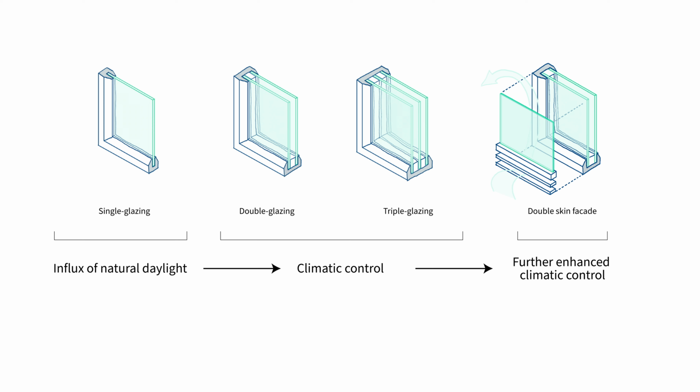The advent of double-skin facades delivered further improvements in thermal and acoustic performance. Double-skin facades incorporate an additional layer of monolithic glazing outside the insulated glazing unit. Natural ventilation is promoted through the external cavity to minimise air conditioning requirements. The incorporation of blind systems or external louvers can further enhance energy efficiency. Some of these systems operate under automated control strategies that may track the sun.